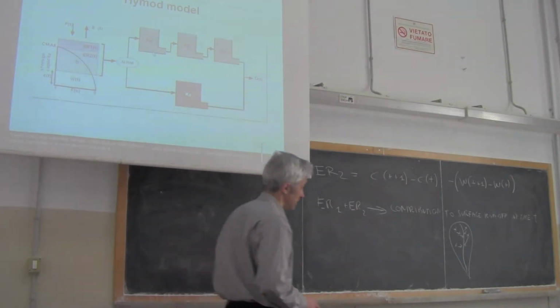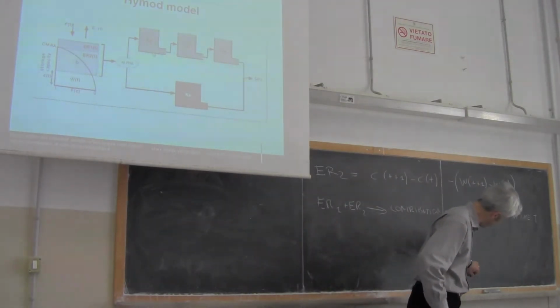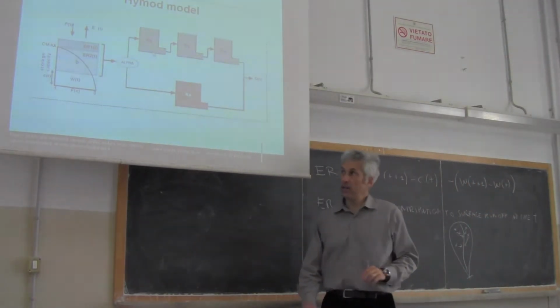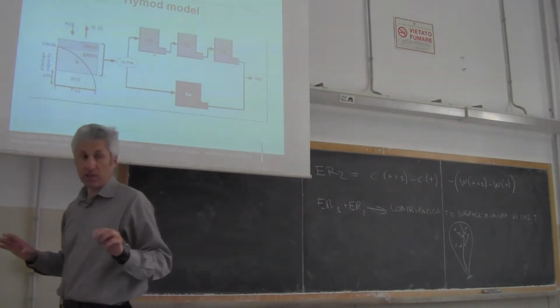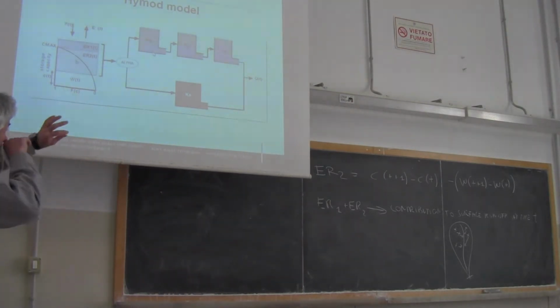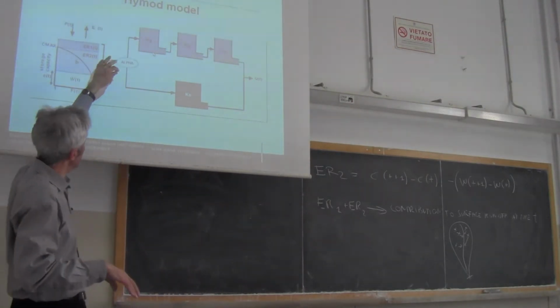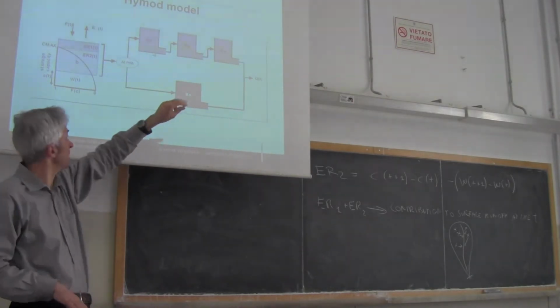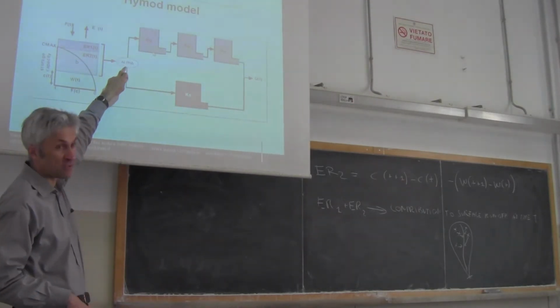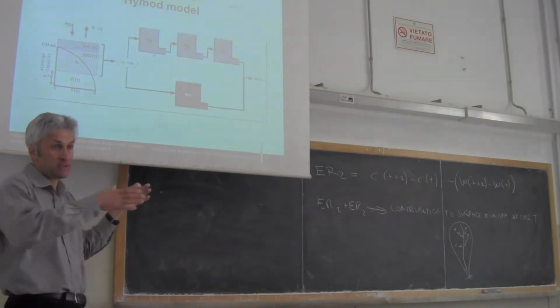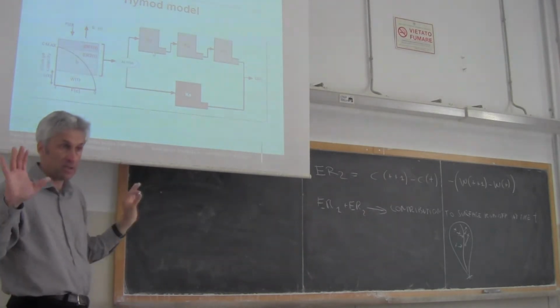The closure is the river cross-section that you find here. And in order to simulate this process, the model assumes that surface runoff is split into parts by introducing an additional parameter alpha, which is a weight varying from 0 to 1.